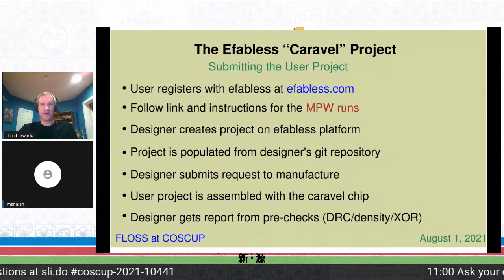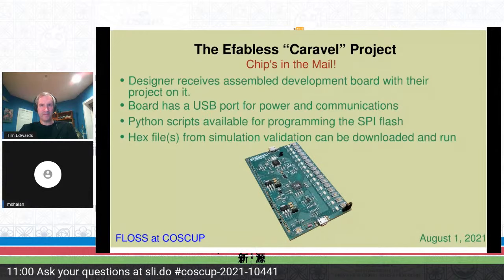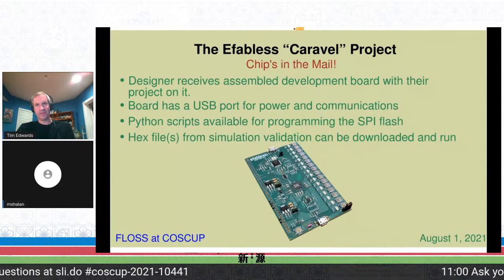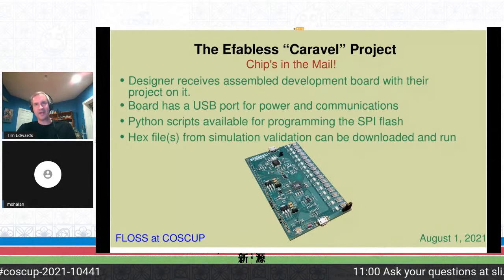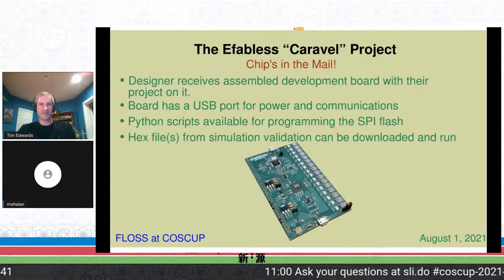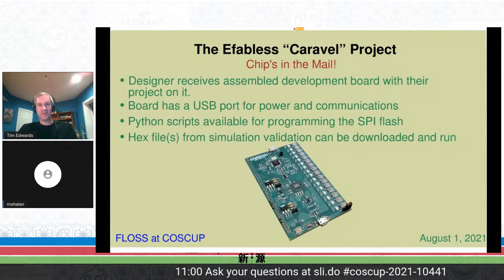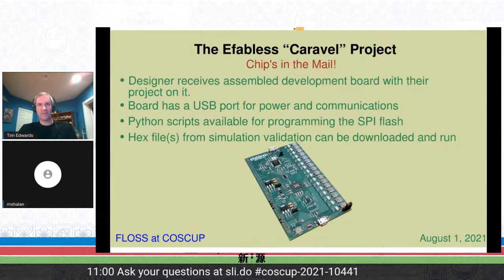So once you get back your development board with the project on it, assuming you've run simulations from the Caravel chip from the top level and you've verified the chip operation, you should be able to simply plug the board into the host computer, and you should have a valid hex program you can download to the SPI flash and run the program and get running.